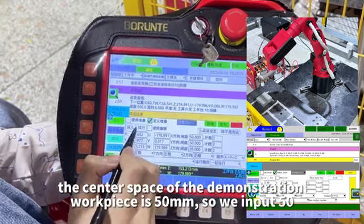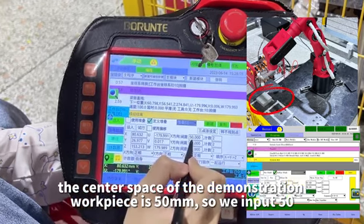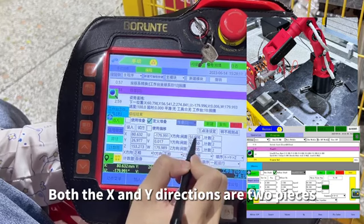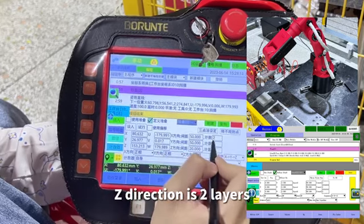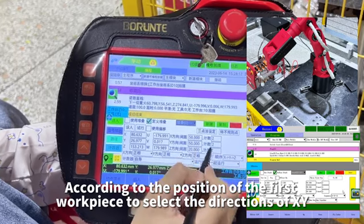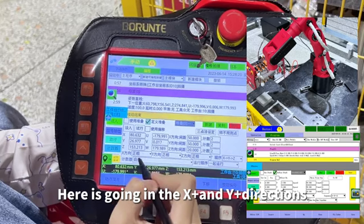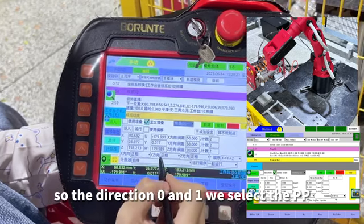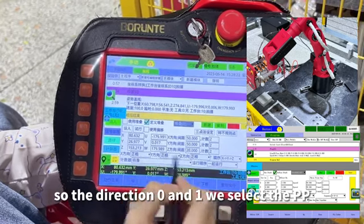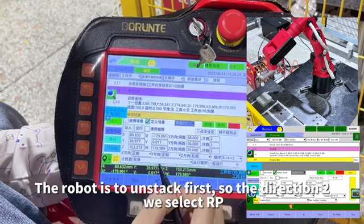The center space of the demonstration workpiece is 50 millimeters, so we input 50. Both the X and Y directions are 2 pieces. Z direction is 2 layers. According to the position of the first workpiece, to select the directions of X, Y, here is going in the X plus and Y plus directions. So the direction 0 and 1 we select the PP. The robot is to unstack first, so the direction 2 we select RP.